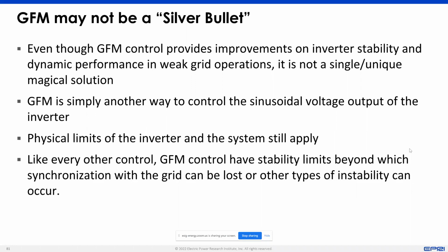And just like how you can have instability with traditional inverters, a grid forming inverter can also have stability considerations. It can also have instability. So it's not a guaranteed fix that just because there is a grid forming inverter, everything will be stable and everything will be fine in the system. A grid forming inverter also needs to have tuning rules. It also needs to be designed properly and so on.